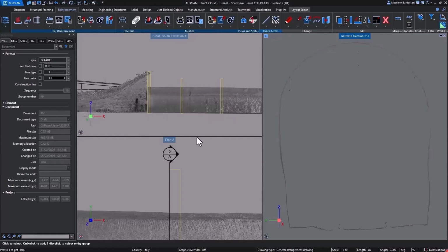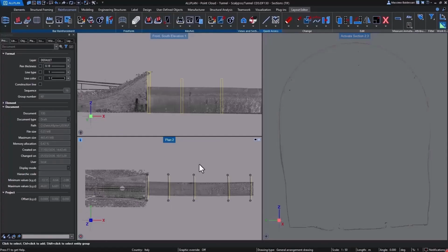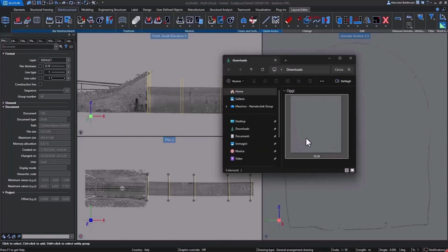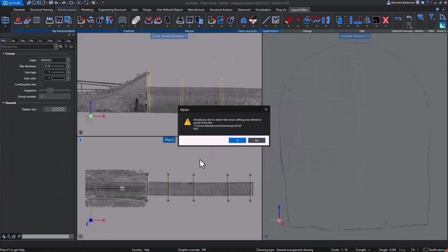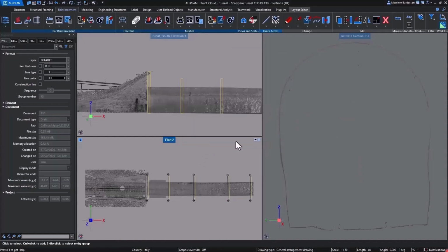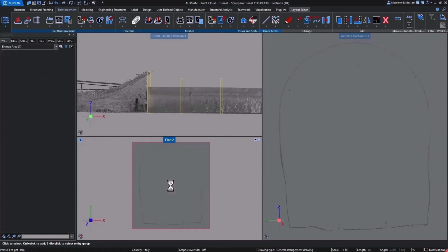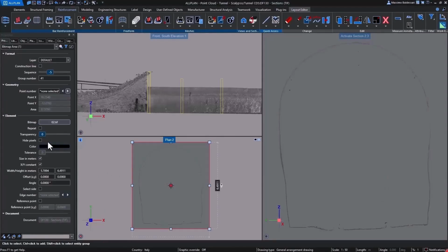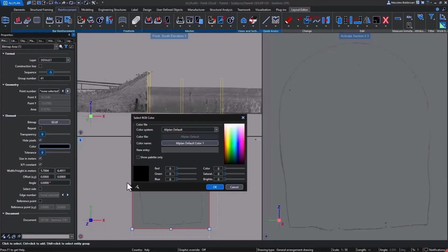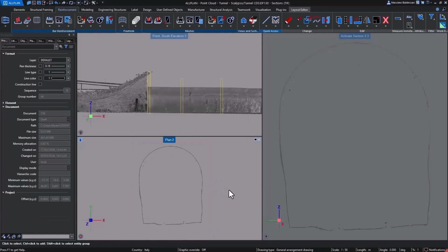Immediately following those steps, I can proceed to directly import my image into the system, which will then be automatically geo-referenced and perfectly scaled based on the actual physical measurements. So we have imported our image. In this case, for the sake of convenience, I will explain it. Go ahead and shift this slightly further down. Once that is done, I can also begin to manipulate my image by making the background completely transparent, and then I will be able to carefully and precisely trace the details directly over the top of my image to obtain all of the specific information that I need for this project.